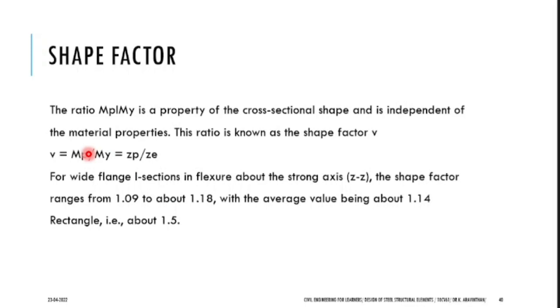The reason we find the shape factor here is that if you are designing your structure for plastic stages, you have to know the shape factor. If you are designing your structure within the elastic limit, what is enough? Moment of inertia is enough. If you are designing your structure for more than the elastic stage, up to the plastic stage, what is important? Shape factor is important. Without shape factor, you cannot find Mp. What do you mean by Mp? Plastic moment, you cannot find.